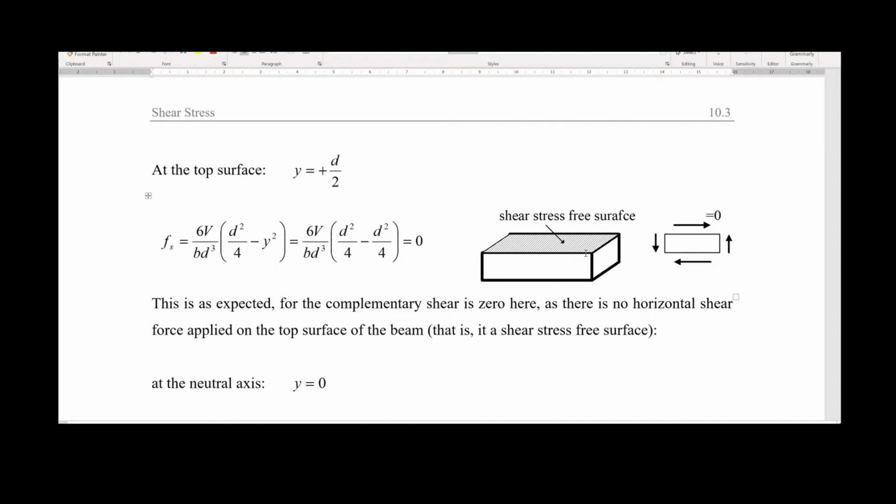So at this fiber on top, you have to have this value equal to 0, if you analyze the first value immediately in contact with the first fiber on top of the beam, because these two have to be equal. There is an equation called the Cauchy equation that says that the shear stresses have to converge to an edge like this, and the values need to be the same.